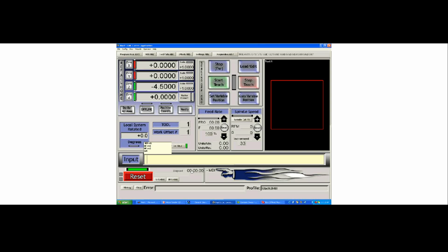From this point forward, M666 becomes a valid G-code command. And when we enter it, we will move at feed rate to 50, 50, and whatever the number was that we put into the Z. And as you can see, the X moves first because that was our first movement line. You can see it's moving very slowly. That's because we told it to move at feed rate.